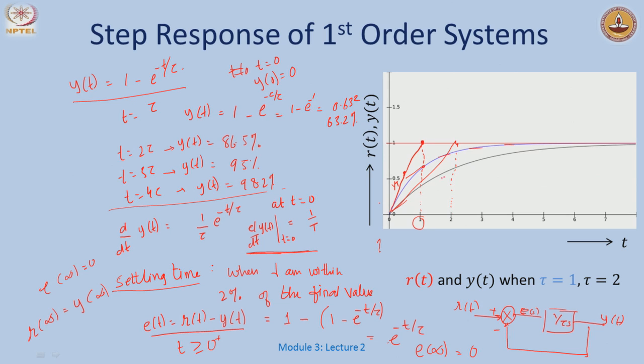No matter what the value of the time constant is, this one is a little slower, but it gets there. You could have even slower ones, but they would eventually also go to the value 1. So this system, and I am sorry for defining these terms early, but we will elaborate on this a little later, has a steady state error of 0. I am running out of space here, but let me write it here. How do I define this? There is a difference between the reference and the output, and how does it go at infinity.